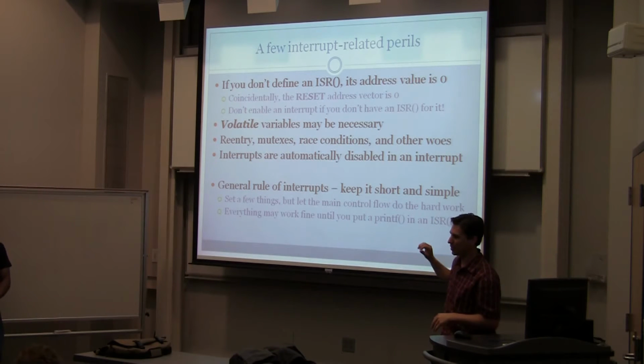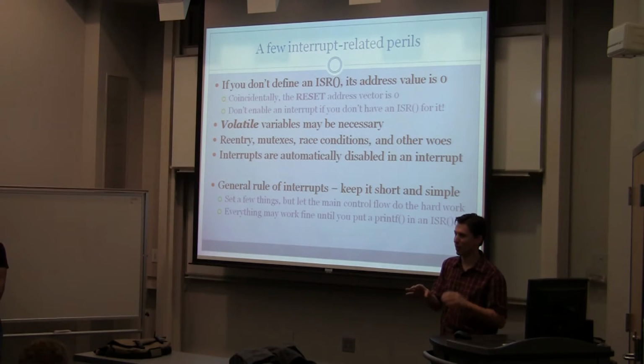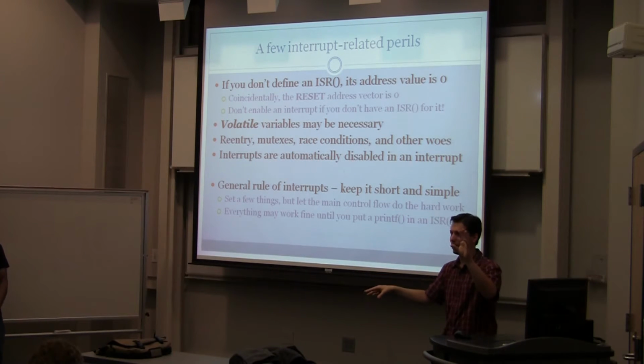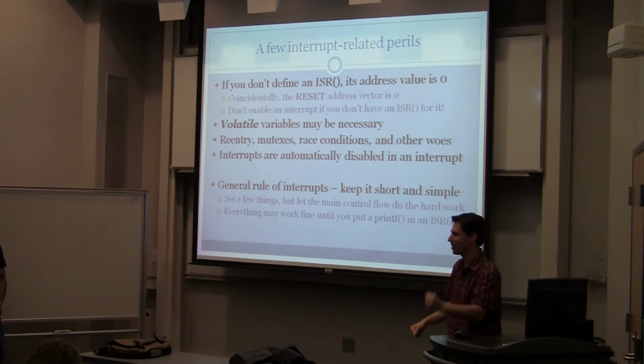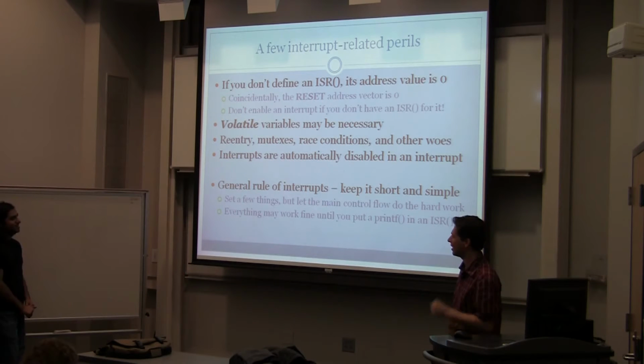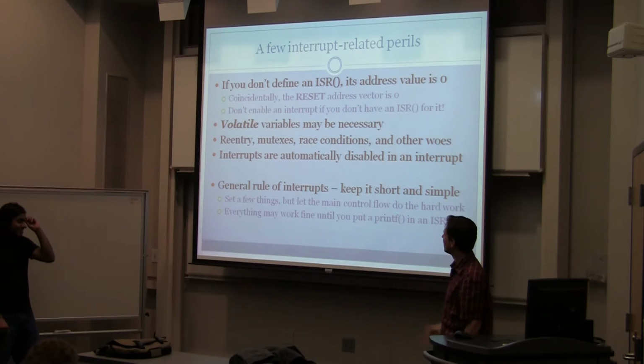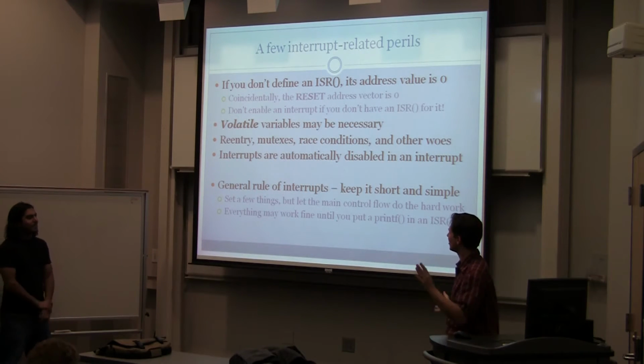So interrupts are automatically disabled when you're in another interrupt. More advanced microcontrollers, I mean, you guys are really using, for 2012, the simplest microcontrollers around, essentially. They've still got a lot of bells and whistles considering, but more advanced microcontrollers have interrupt priority, so you could say this interrupt is more important than this one, deal with it, even if you're inside this one. That's good for your emergency stuff. You want that stuff to be highest priority, on fire, that kind of thing.